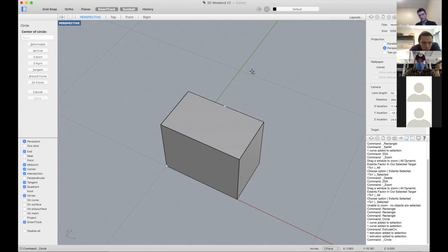So at any time, if you're using Rhino and these little white things don't show up when you get towards the edge, where you see it saying all kinds of things when I go over this line, whatever command you have up, just type osnap, and that is your object snaps.